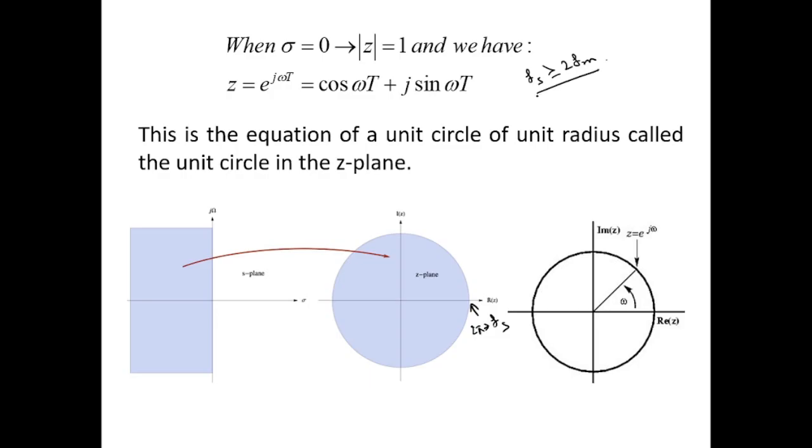So under the restrictive condition, what will happen? Fs should be equal to 2 of fm. So fm should be equal to fs by 2. So it should be placed at pi. So at pi we will be having fm. That is the maximum frequency within the signal.